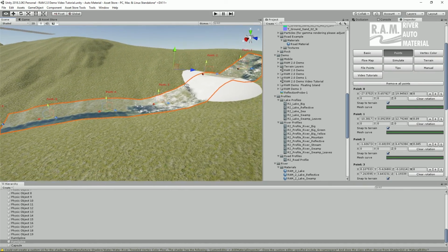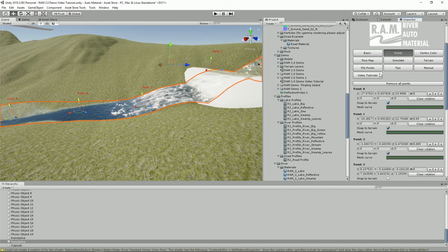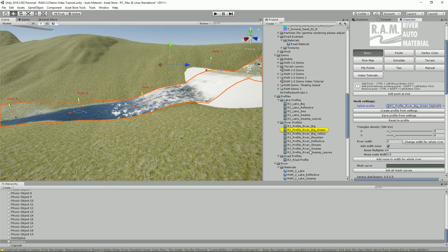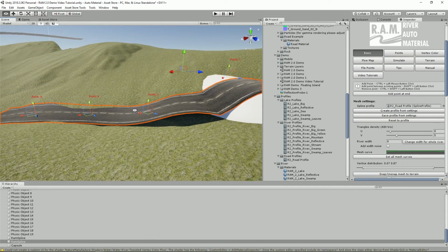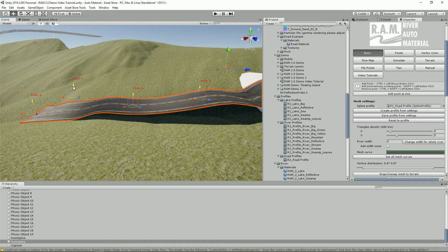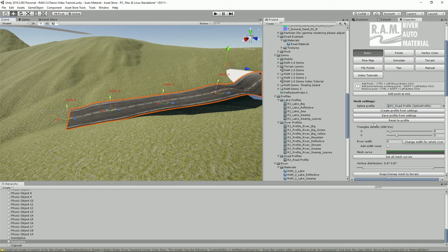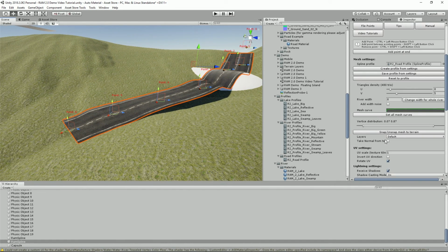You could change snapping also per point. So you simply choose a point and unsnap or snap it. As we see, when we choose the road, for example, and move a point which is unsnapped, we could freely manage it, and a snapped point still sticks to the terrain. It only changes normals, which also could be pretty useful. You don't change the position and you get different normals from the spline.